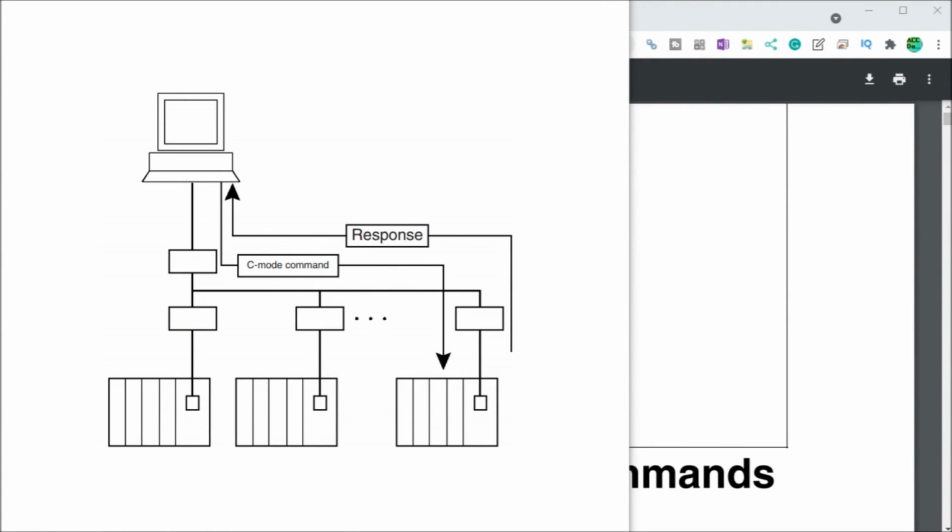Hi everyone. Today we will be looking at the Omron PLC Node-RED serial communication. Now PLC manufacturers have their own proprietary protocols. These methods of communication will allow you to program the controller. Other protocols will allow you to collect and log information for programmable logic controllers. Node-RED has the ability to read and write to the Omron controller using some of these special protocol commands.